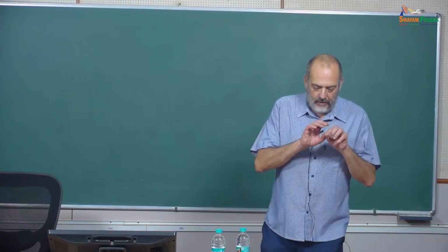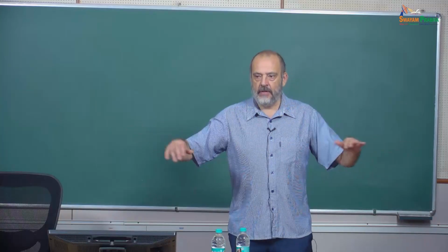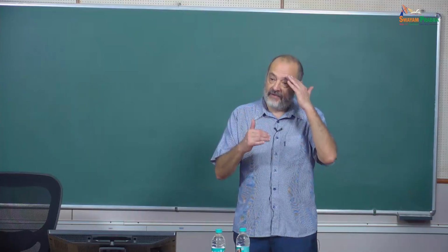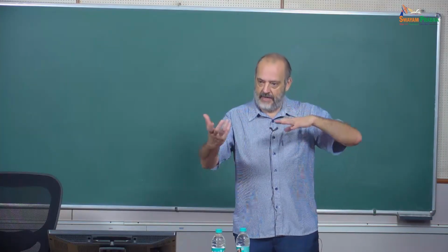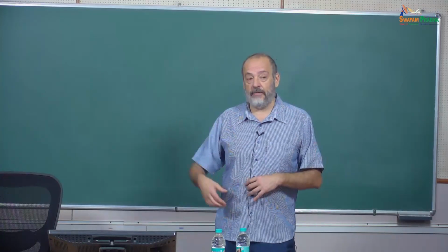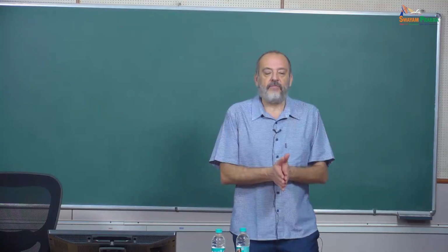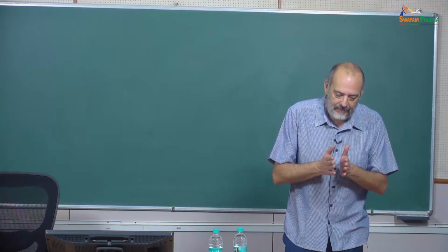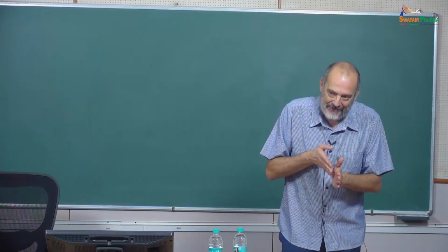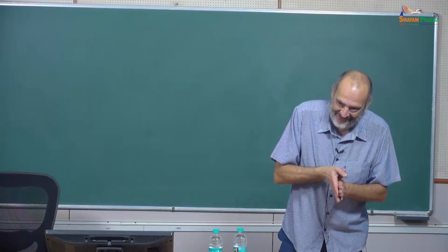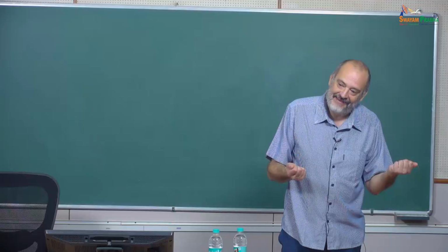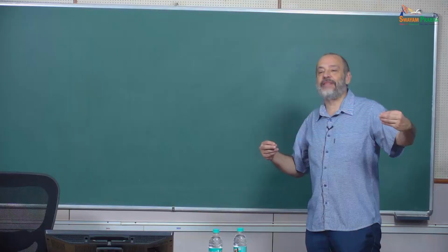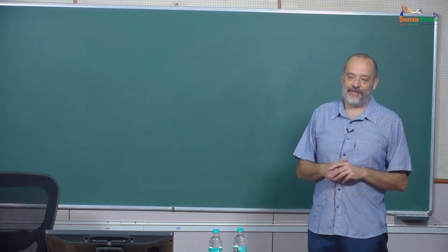So if you're doing a VOF simulation, this must be correct, no? Because you're considering the interface. When you're seeing at the macro scale, so you're doing, for example, Eulerian, we know that from the experiments we saw a different velocity. But in fact, we saw the different velocity because we are not able to go to the nanoscale. So the scales are different. If you're going to the nanoscale, if you're doing molecular dynamics, you will see that there is a transition not only of the density, but there is a transition of velocity.